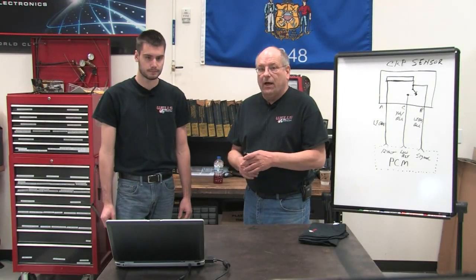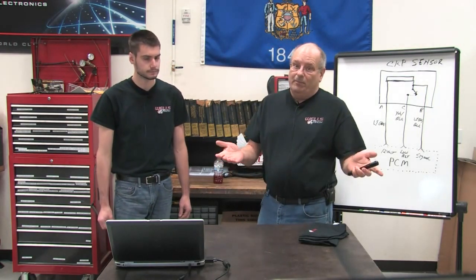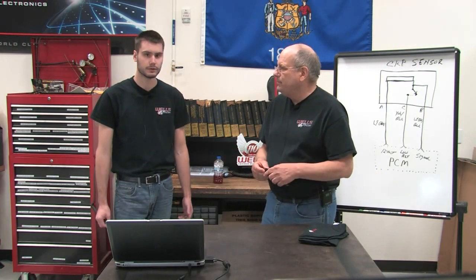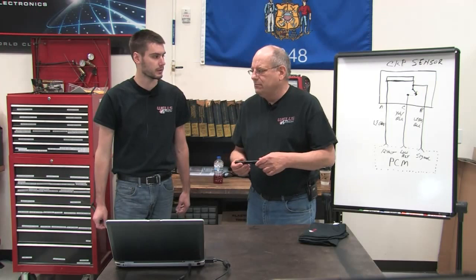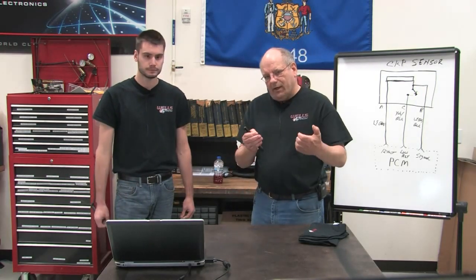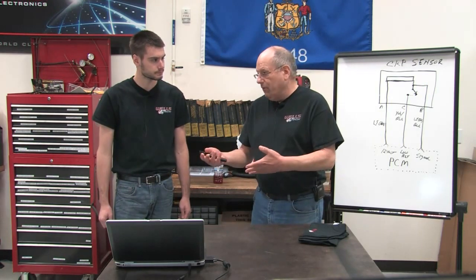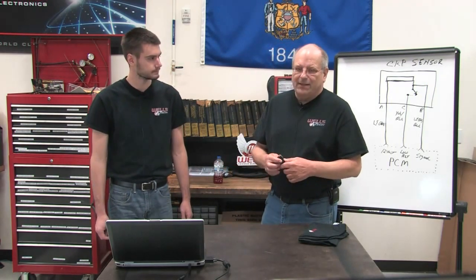And we replaced the sensor. Now, when you replace the sensor, there's a little tip. If you don't know, you need to do this because it'll save you tons of time. When you're replacing that sensor, you don't have to unbolt the lines off the power steering pump or anything. Just unbolt the pump and slide it out of the way. Just move it a little bit, and then there's enough room to get in there and pull that cam sensor out. It saves you a little time that way, and some headaches.